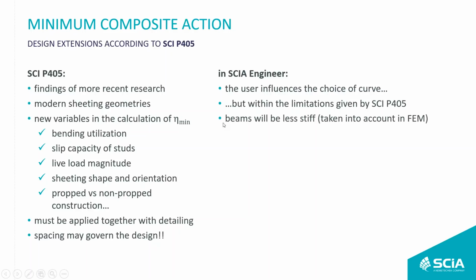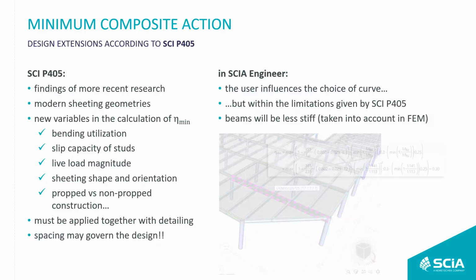Also, by using fewer studs, we will have beams that are less stiff. So your composite action will affect your deflection. And this is also taken into account in SCIA Engineer on the level of the FEM analysis.